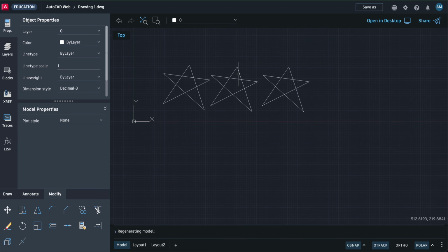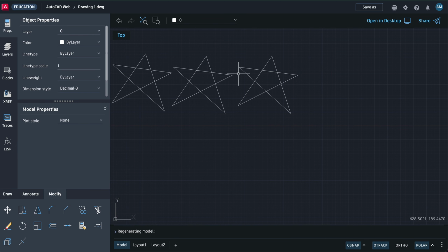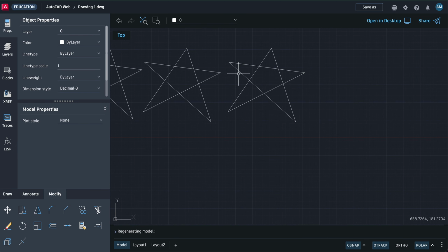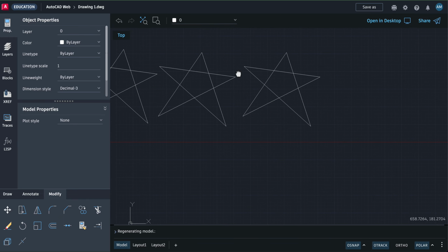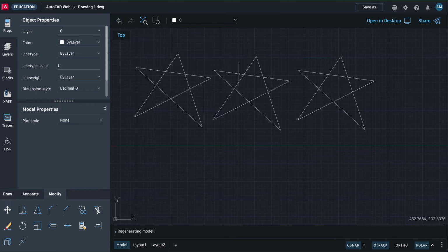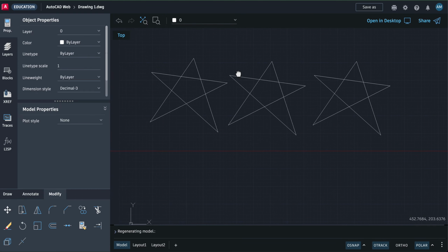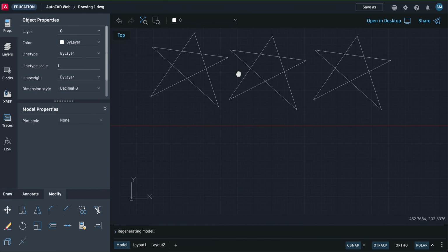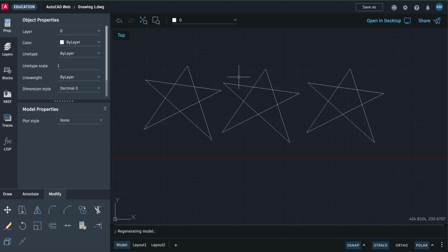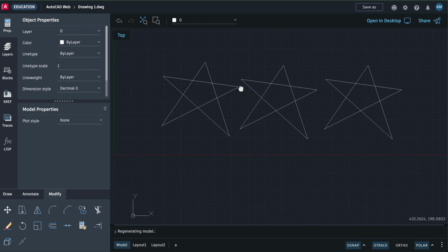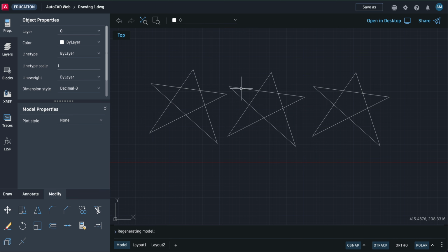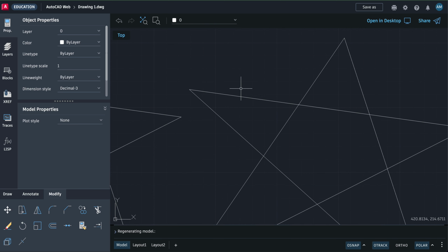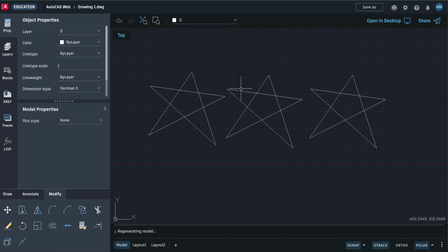But if your two fingers go up or down immediately, you're zooming in and out. So pan, P-A-N, is when you press two fingers and then simply drag to the left or right. Then you can move your screen left and right. You can also move it up and down, but the first motion should be two fingers left or right. Then you can pan. Because if your first motion is two fingers up or down, you're zooming. Okay? Let's continue the discussion.